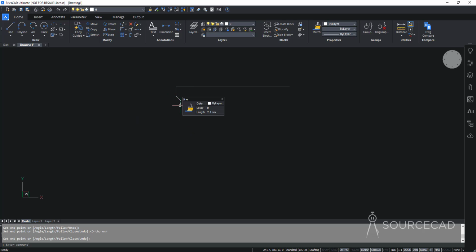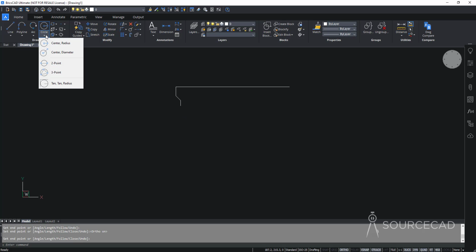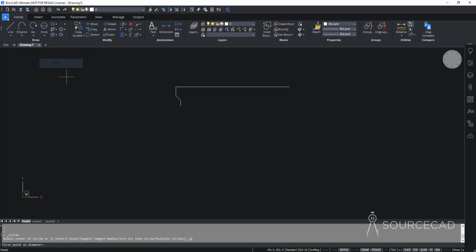Now I just need to make a circle here. So I'll go to circle and I'll select 2-point circle, this point, and then right along this direction I'll make a circle of diameter 7.2 and enter. So 7.2 is the diameter from this point to this, and we can start the line tool again. So now I'll track this point carefully, click here, and now this length again is 8.8, enter, and once again 2-point circle from this point, and right here it should be 7.2 again.